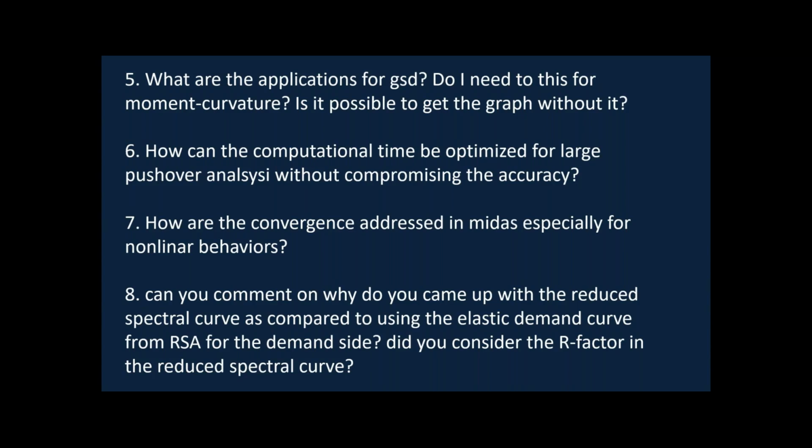And to address the second part of the question, did you consider the R factor in the reduced spectral curve? The answer to this is yes. As I'm considering the demand, I'm reducing it by the R factor to compute the spectral curves.